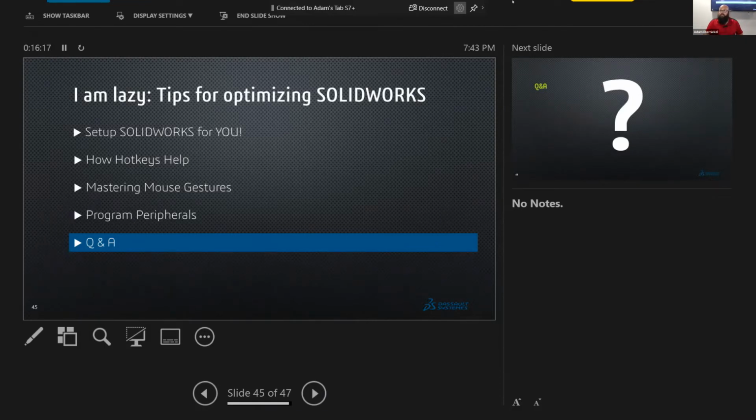I'm not sure if it's interconnected or not. It may not be, but we're also working a lot better with those solid models. Yep. That's the direct editing is what I do a lot of. We'll get a model, and then suddenly you convert the STEP file to a model, and there's 1,000 broken faces. And what do you do? You spend a week. I think SolidWorks is realizing a lot. Heal gap, delete face.